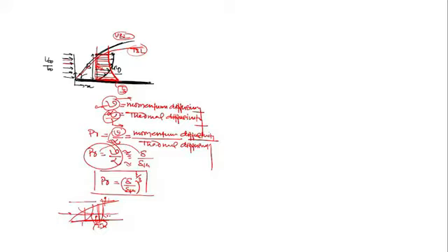So what I'm saying to you is, the contribution due to bulk flow motion originates from the fact that the boundary layer grows as the flow progresses in the x direction. Since it grows, whatever heat transfer through conduction is taking place, the heat that is conducted into this layer, I'm talking about the layer above the surface, is swept downstream, swept away, because the fluid is in motion. Whatever heat has been conducted is swept away downstream.